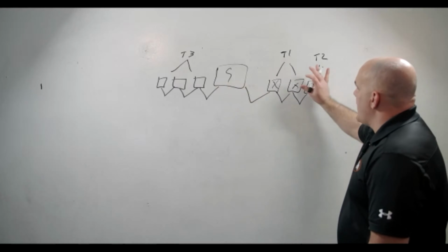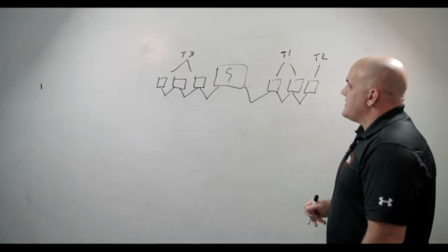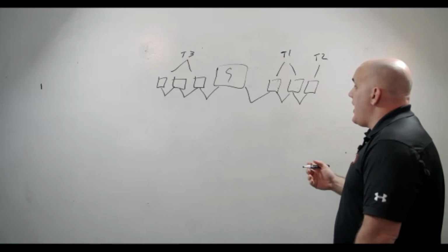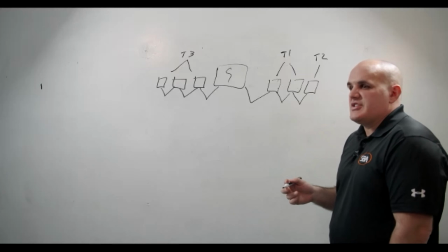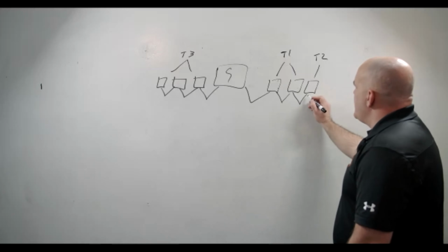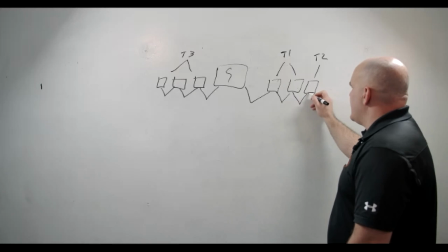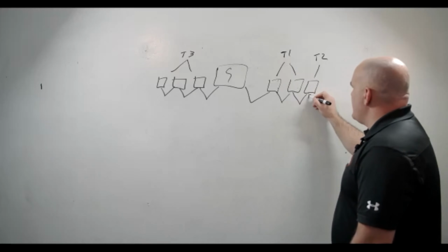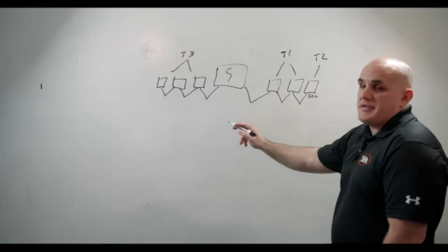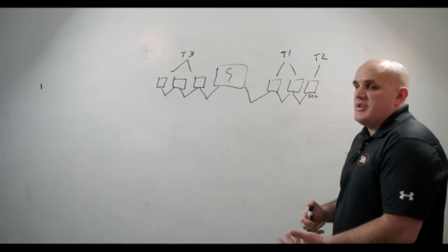So that's our first issue, power. Now, unfortunately for us, end-of-line issues can look very similar to power. An end-of-line is actually a resistor that dampens the reflection of the signal. Because of how serial communication works, when that electric signal hits the last controller, the end-of-line resistor dampens the signal and keeps it from bouncing back, and that bounce back would interfere with communication.